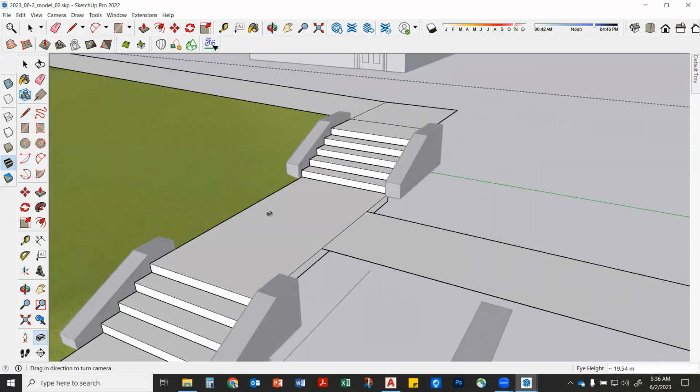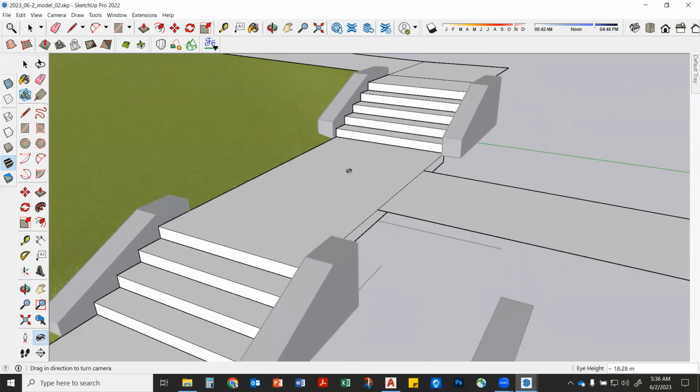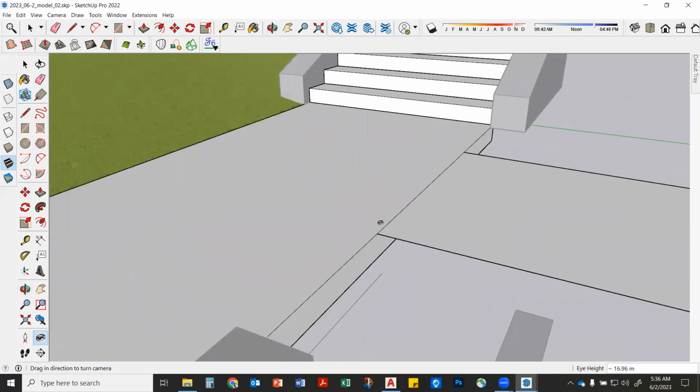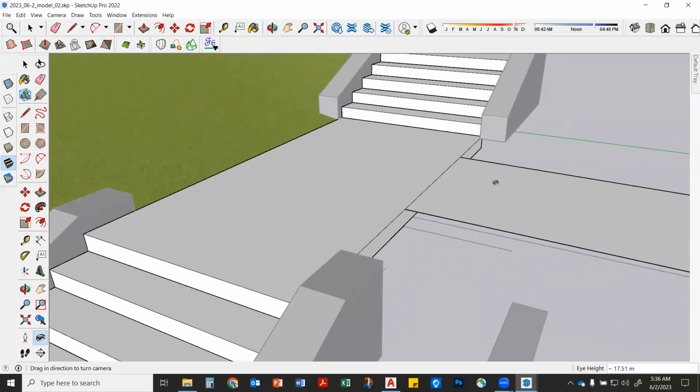This is tying into site engineering too, which is why SketchUp's so good, because you have to solve these problems in 3D, right? The reason we didn't have to make a cut for this one is because this isn't sloped, is it? When we modeled it, we didn't slope it by 2%, right? Remember you come down the stairs, then from the bottom of the stair to the other part, we just sloped that. So we actually have to warp our walks a little bit to hit that slope. This one's flat.